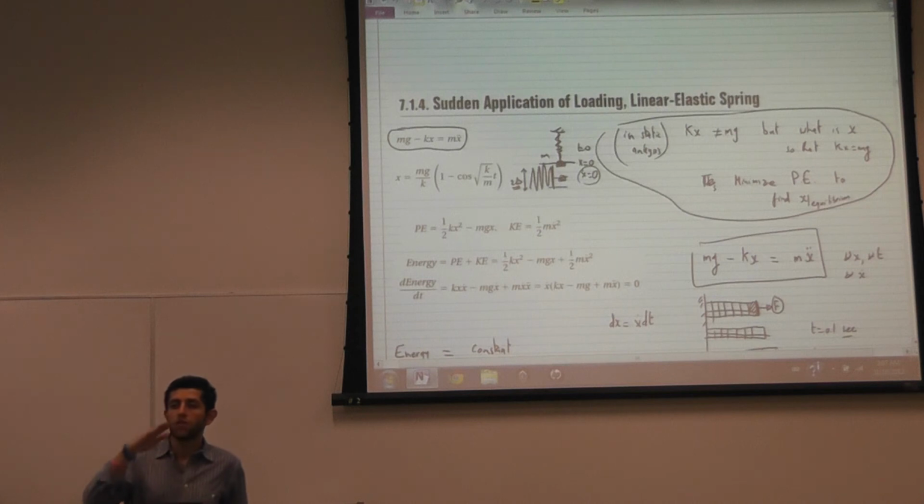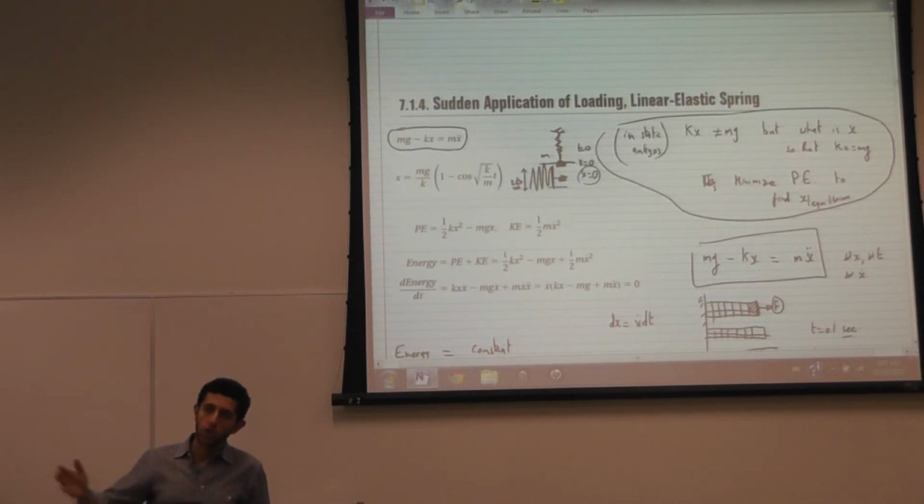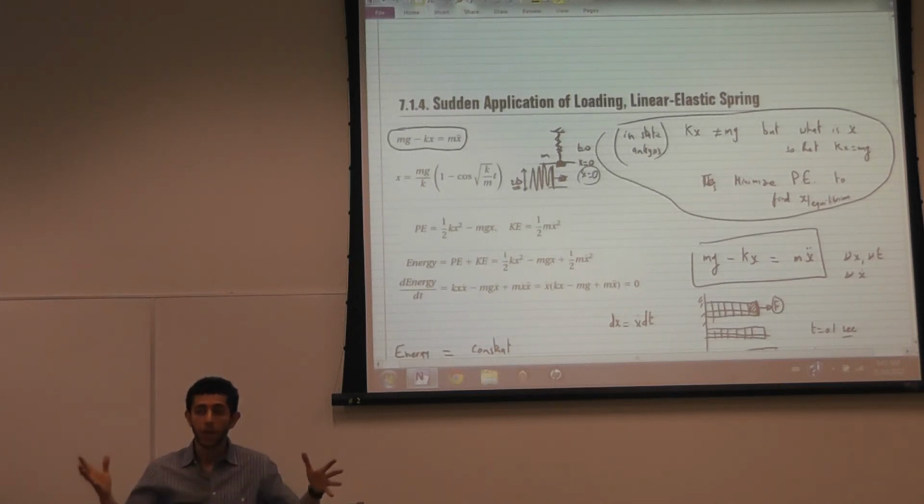If the bridge is vibrating already, and as it's going down you impact it, then sure, the dynamic factor is higher. But if the bridge is stable, starting from 0, and all of a sudden a car appears, with no impact, then the maximum dynamic factor would be 2.